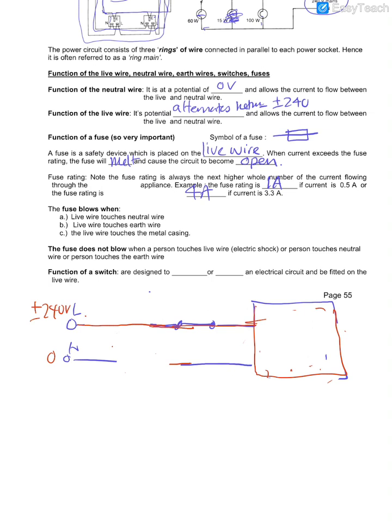So the danger is, if I go and open this up and meddle around, try to fix anything, and I come into contact, let's say, with a live wire, what will happen to me? I will die. I'll get a very bad electric shock, may even die, right? Why? Because the appliance is still considered live. It's still at a high potential.